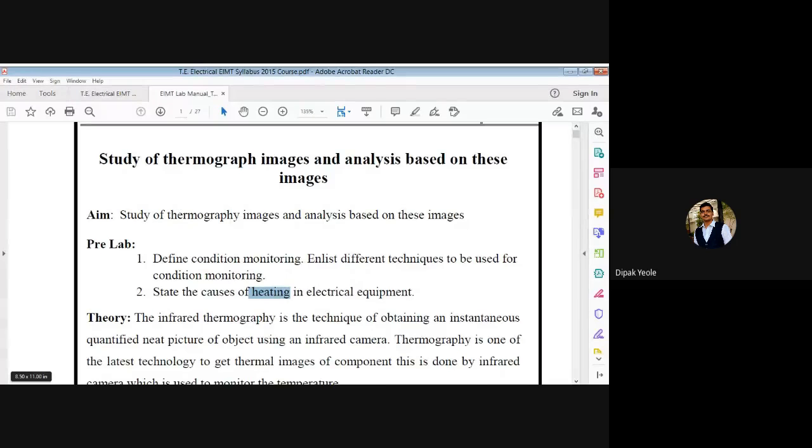Yes, so you have to see the image. After seeing the image, the heat is obviously going to develop, the hotspot is going to be identified, and you have to check that hotspot against the real condition. So obviously you have to dismantle that electrical equipment, power off the connection, and find out at what point exactly the heat is developing.